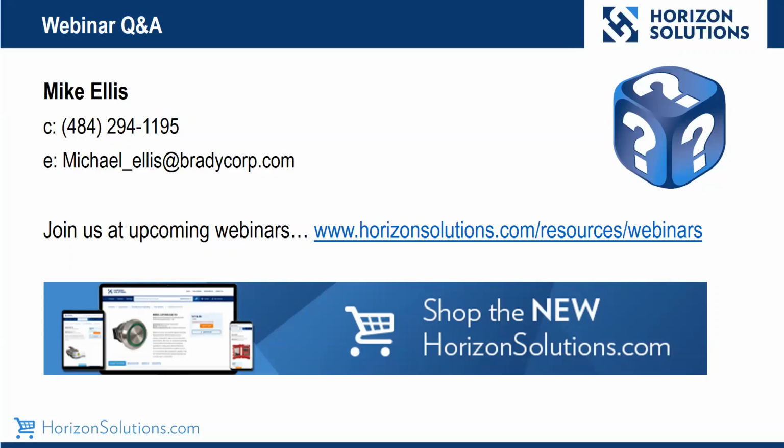Here's another one. This is my kind of question. We work on a lot of low voltage circuits and equipment. Do we need to worry about arc flash? Jim, do you know the answer to that question? I think we do need to worry about arc flash at anything over 50 volts, according to OSHA. Good answer. That's exactly what I would have answered. And there are low voltage circuits that have high amperage also that could pose a hazard.